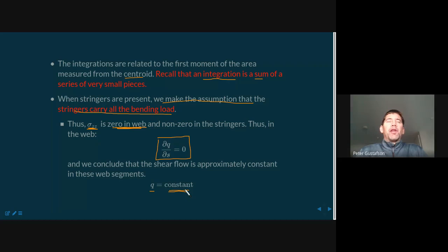I would say most of the time with aero structures, we're going to have skins on the wing or on the fuselage that are going to be relatively thin. And the principal load-carrying members, so this would be the spars in the wing or the longerons in the fuselage, given the need to carry substantial bending loads, are generally going to be quite thick, big and bulky in comparison to the skins.